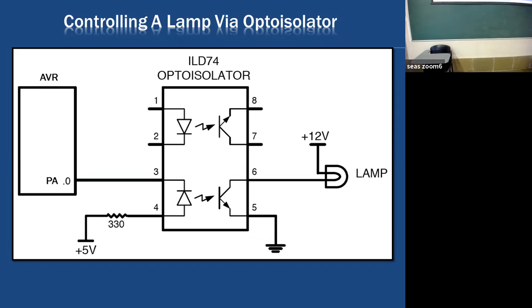So this is an opto isolator. It operates optically, and it isolates both sides of the circuit. You turn this on through current on this side. The light emitted from this diode will complete the circuit on this side. So it isolates both sides of the circuit and does so through light.